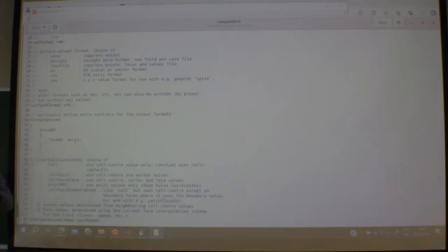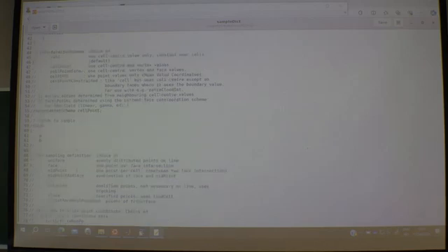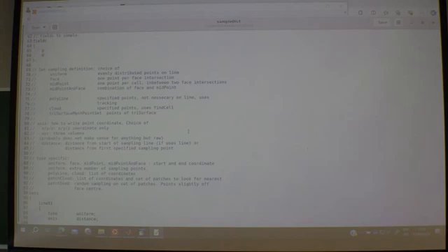Format ASCII, I think that's default anyway, so I don't think you need it. But yeah, it should be ASCII, of course. And then here, what fields to sample? This is important. I mean, here I specify pressure and the velocity. So he will load that one into memory and then start, say, extracting data from these fields. And then you can choose a whole bunch of different things. Plot over line, plot phases, plot along any polyline, for instance. You can do whatever you want here.